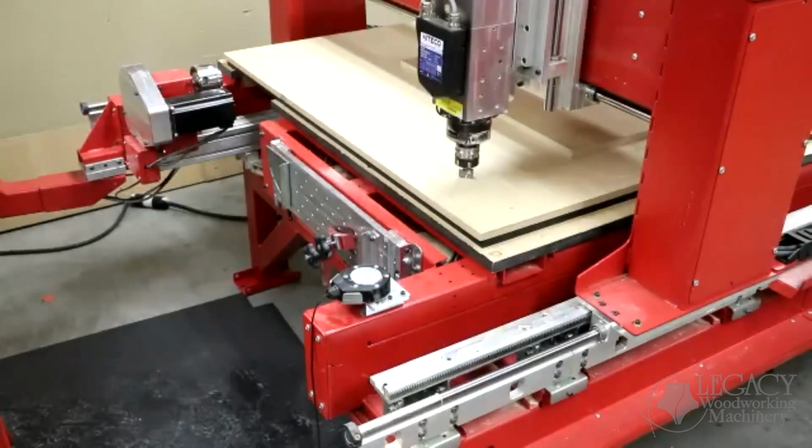Okay, can an old style smart tool pad develop dead spots? Now if your pad is on a Mach 3 system, so it's not a proximity pad, if it's just contact, then it has to conduct the circuit. You can get dirty collets, gook or sap on your router bit, tips of your cutters, anything so it doesn't conduct. Then you wouldn't really have a dead spot. You'd have it just not always contacting.